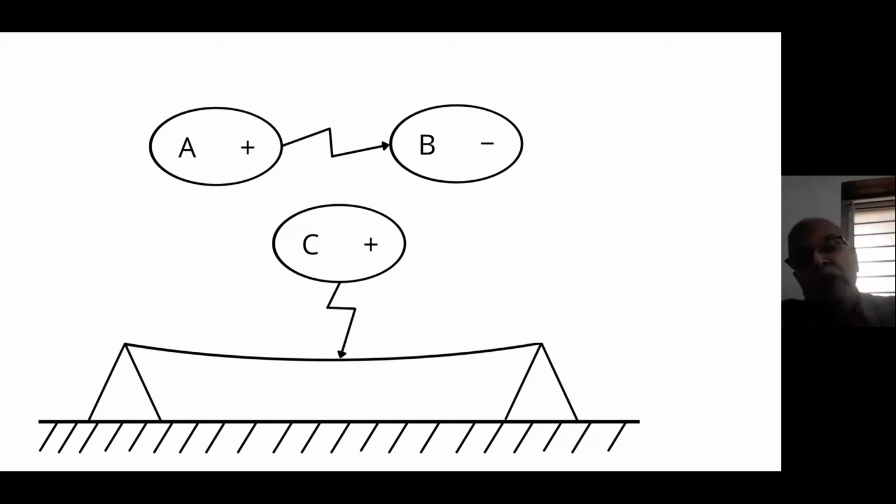What is direct stroke type B? This is direct stroke type B. I have got two clouds, B and C. B is negatively charged. Therefore, C is positively charged by induction. Now, that induces charge on the transmission line.